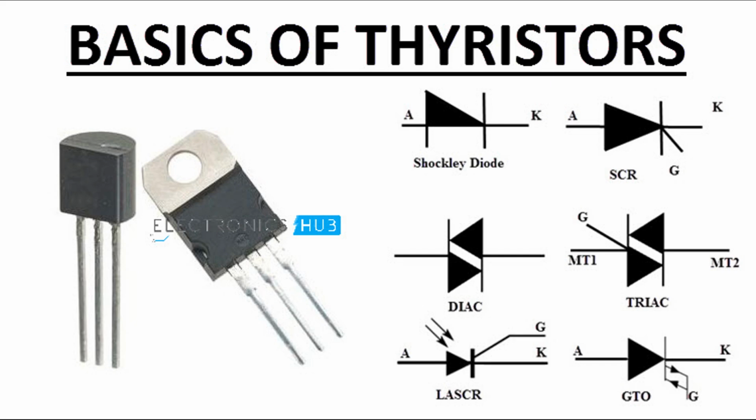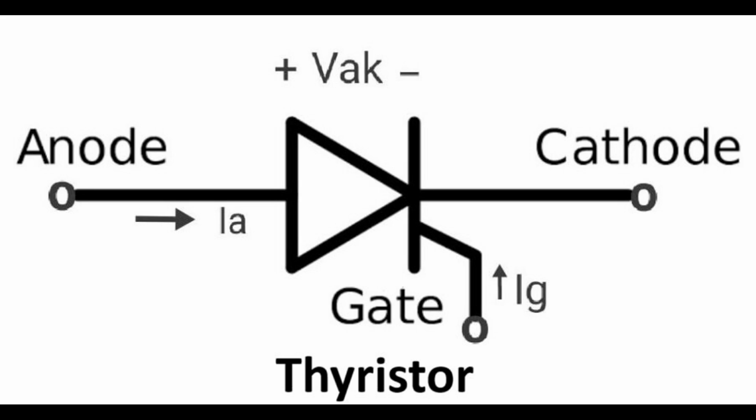In a remote light-activated switch application, the LASCR can be used as follows. Initial state: the LASCR is in the off state, blocking current flow. Light trigger: a light source, e.g., LED or laser, is activated, illuminating the LASCR and triggering it into conduction. Current flow: the LASCR conducts, allowing current to flow and powering the load, e.g., motor, lamp. Turn-off: the current through the LASCR is reduced below the holding current, turning off the device.